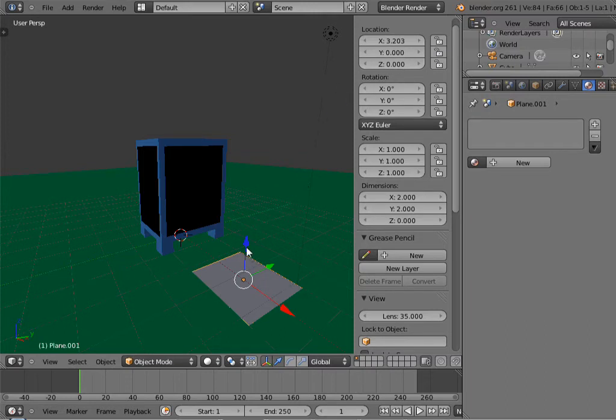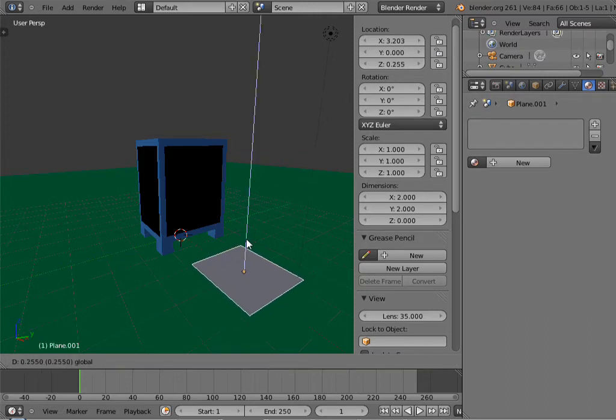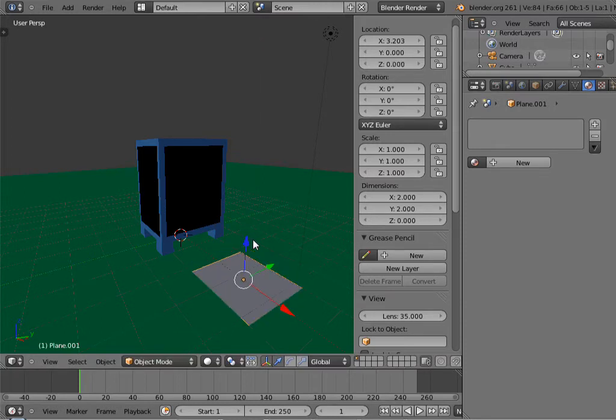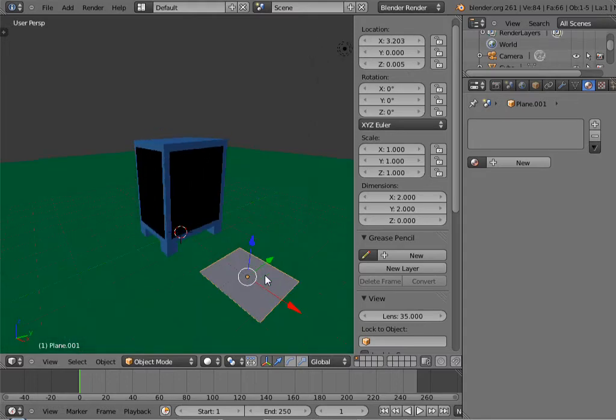So rather than manually bring it up, which can be very fiddly, and you might get too much separation so it looks like the road is floating, I'm going to go in here and add in something like 0.005 there, and that's basically unnoticeable, but it's enough for the renderer to know which one is on top. So it will never draw the grass on top of the road.